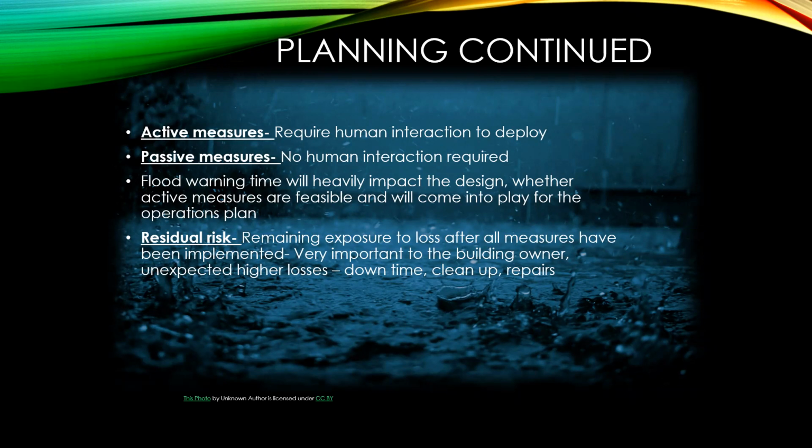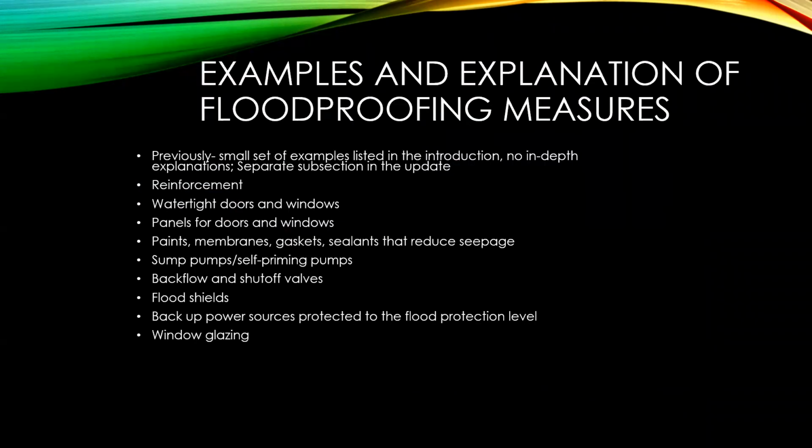And again, there's a lot of things that can go wrong. So failure could be due to unidentified points of entry, poorly maintained floodproofing products or measures, or a miscalculation on the flood loads, or again, a larger flood. So there's just a lot that could go wrong. Someone didn't deploy the measures that they were supposed to, or it wasn't done correctly.